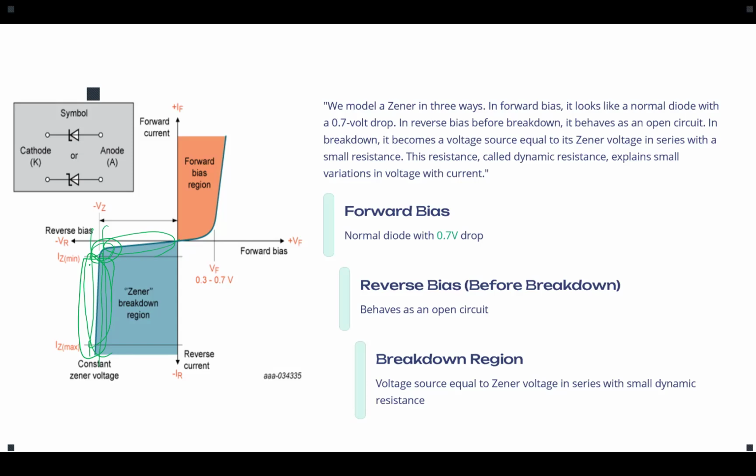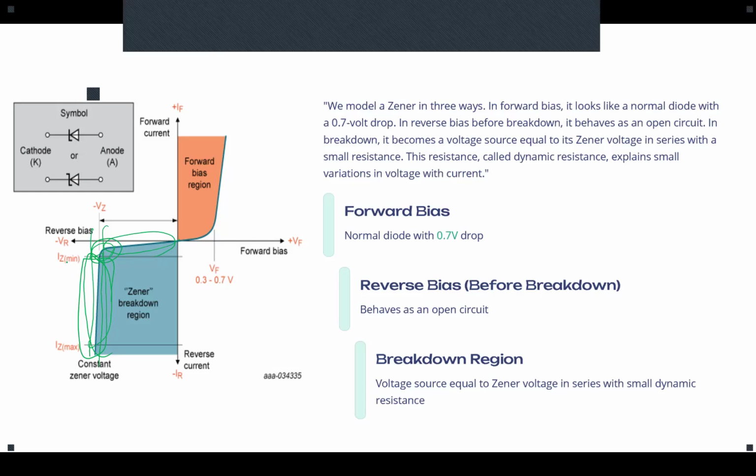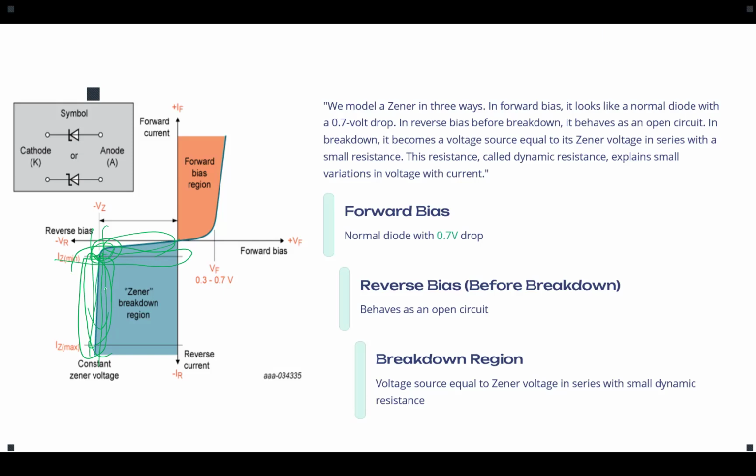So when we set up the Zener diode, we should set the circuit in a way that we have a certain minimum current going through the Zener diode, so we pass that knee section and go to this constant voltage drop section. When you're working with a Zener diode, it's not just the reverse biasing. You need to set the current above the minimum.